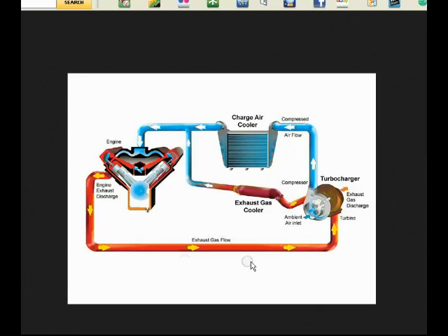We have ourselves a turbocharger here. Here is the engine intake on the top, and then here's the exhaust manifolds. So airflow goes in, drawn in, compressed with fuel, ignited, compressed power, exhaust. So that exhaust wastes heat. That's at least 1/3 of the energy in the fuel. But instead of just going out to the atmosphere, it then goes to a turbocharger hot section, the turbine.